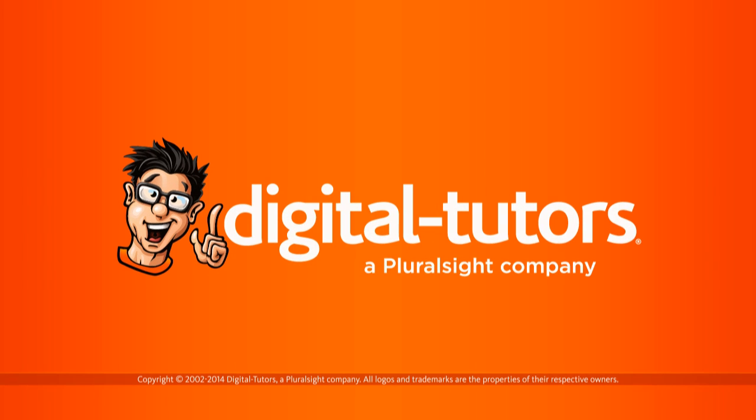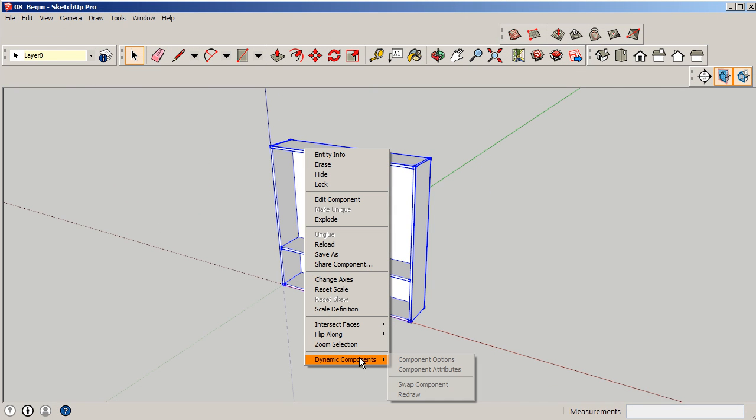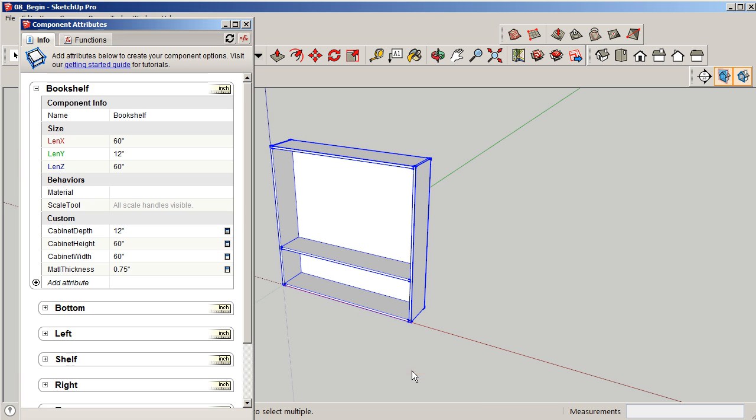In this lesson, we'll begin applying formulas to some subcomponents. Alright, so we should have every component in place. So go ahead and click on it and right-click your element. So we should have our component with our subcomponents. If you go to Attributes, we should make sure that each one of these options here are custom. Our depth, height, and width are all set to the option mode using the Details box.